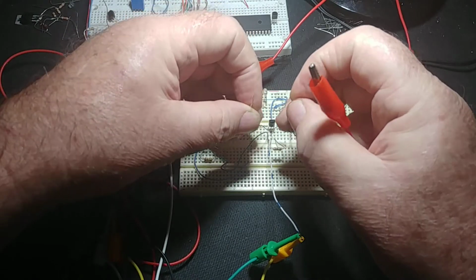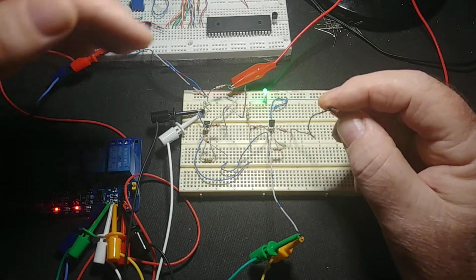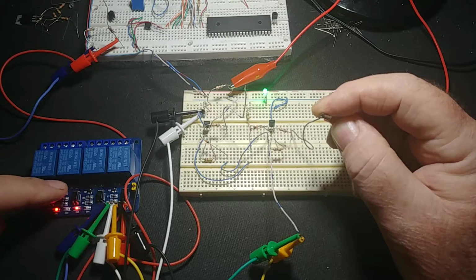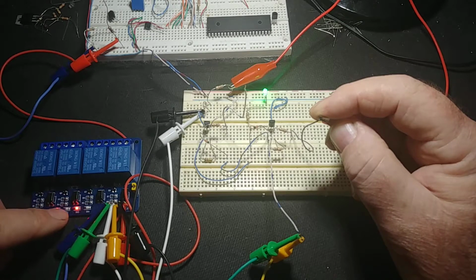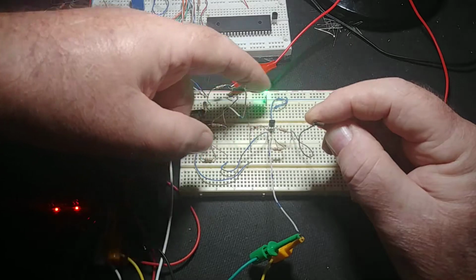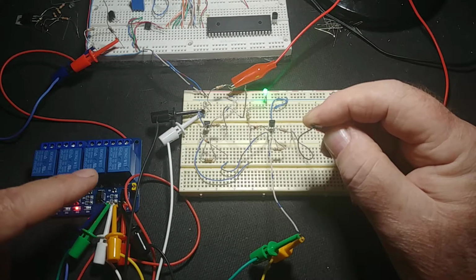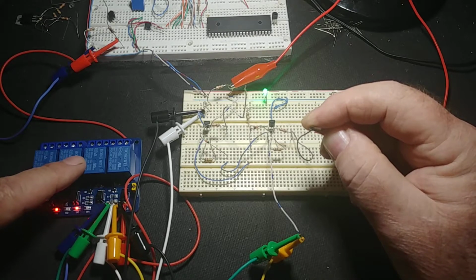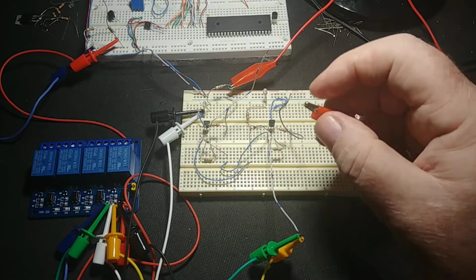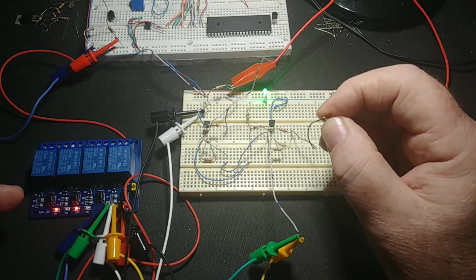These are the two inputs. So if I put a positive on this FET, you can see the green light, it came on and it switched the relays. This is relay 1 and relay 3. Now current flows from the FETs, negative current flows, the electron current flows from that into the relays to turn them on. So it takes a 0 to turn on the relays. And I'm saying a 1 in my circuit turns it on, which is good because then I can have the microcontroller just produce a 1 and it'll turn it on.